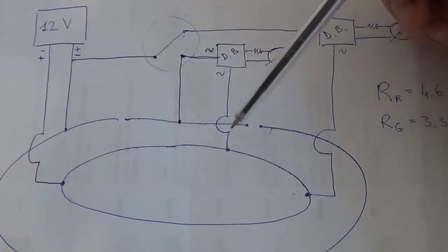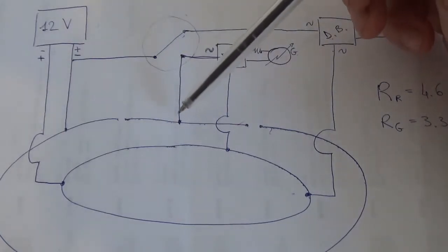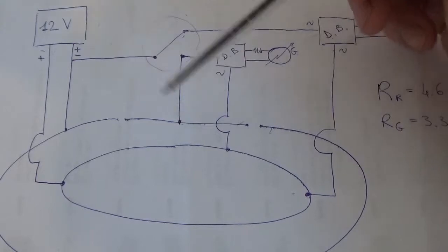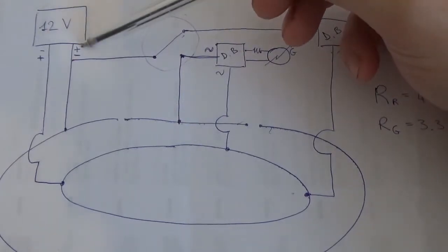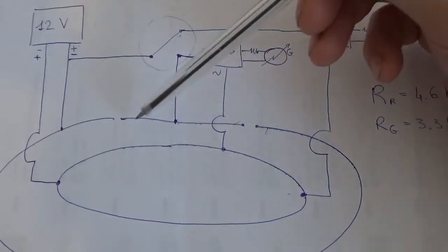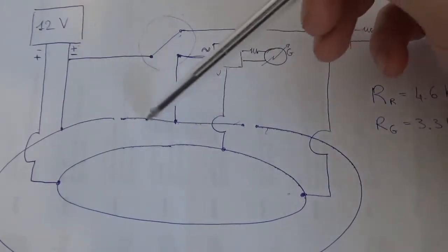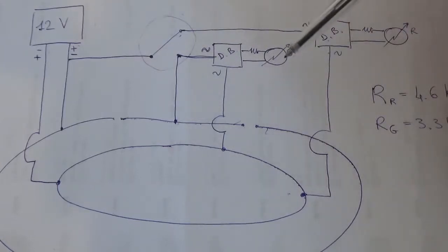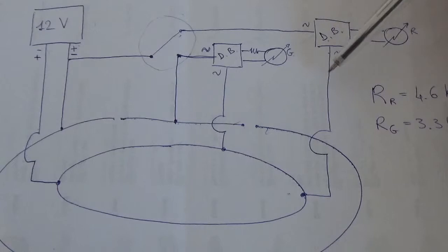Once again, this circuit is considered open, therefore even if we change the polarity of the power supply, we still have no voltage over here in this section. The green LED is off, and through the diode bridge, now you understand why I had to put it, we still have the red LED on, even if the current is flowing the opposite direction through the inputs over here.